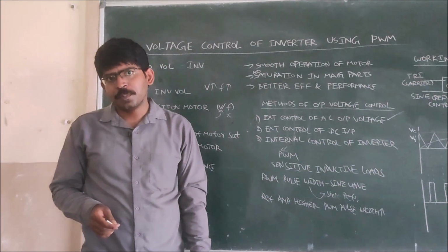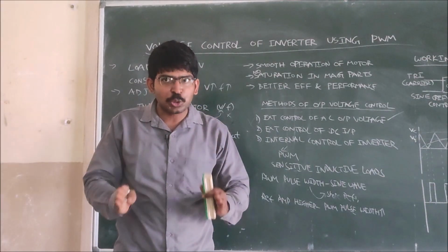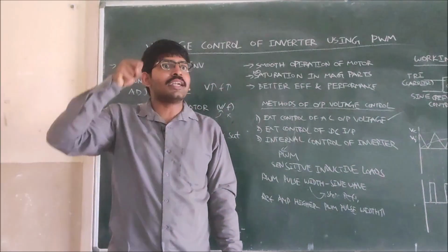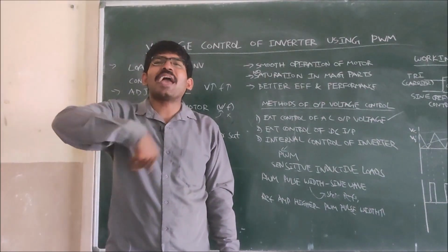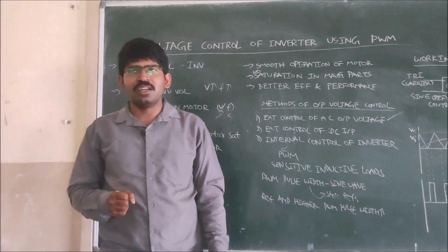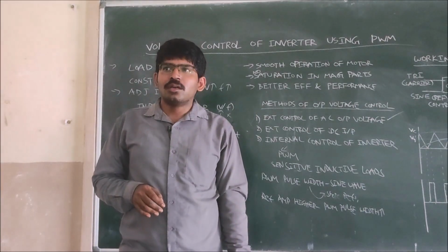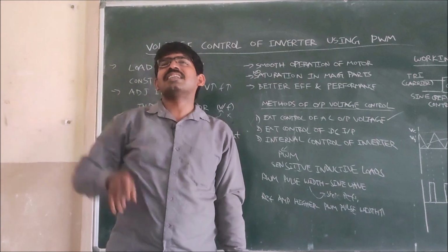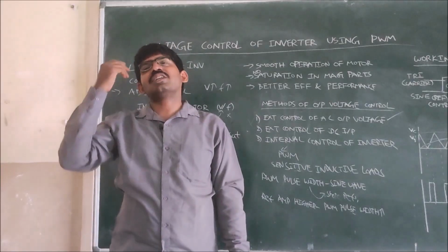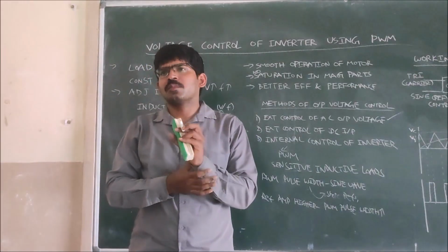Then obviously, the magnetic parts of the motor, they will get saturated. Means they don't have the ability to store more magnetic field. That remaining magnetic field forms the heat, because energy is neither created nor it is destroyed. This heat will damage the motor. Because the voltage is increased drastically, magnetic parts are in saturation mode. That caused heat there, in turn it damaged the motor.